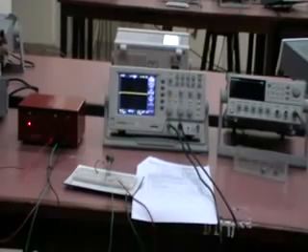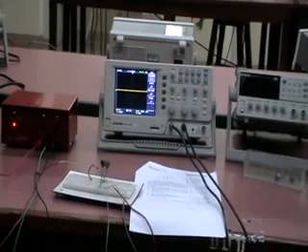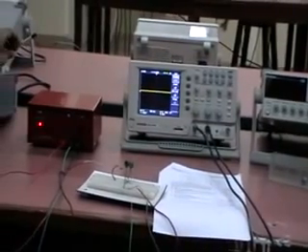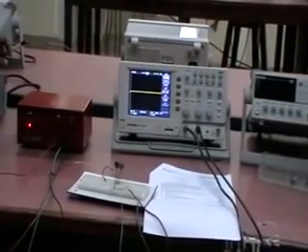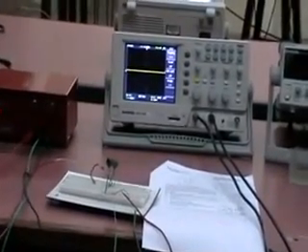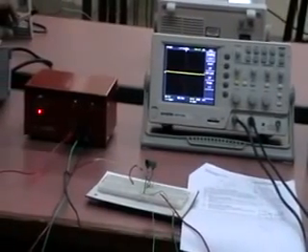We are going to do this in two cases, with capacitor and without capacitor filtering. Before starting this experiment, we should take some precautionary steps before connecting the circuit. The circuit that we are going to connect will provide enough power to heat some components and burn them or even blow the fuse. So we should be extremely careful and ensure that your wiring is correct, and there should not be any loose contacts, and all the contacts should be firm. At no point in the experiment should the outputs of the transformer or the rectifier be short circuited. So these are the precautions that you should take.